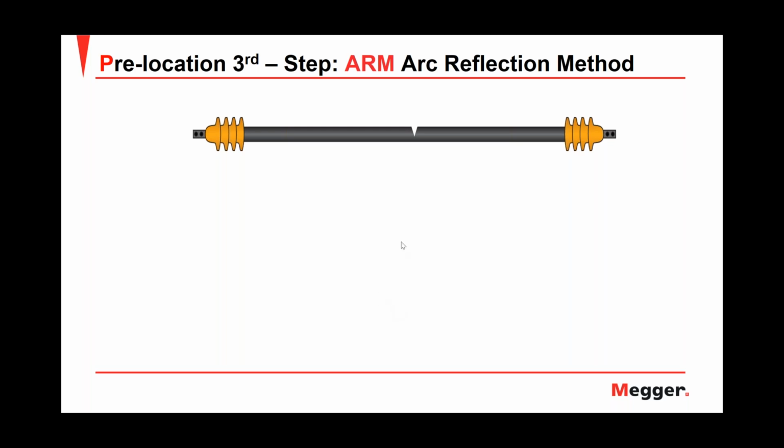Let's consider that we have a medium voltage cable. Let's say that it's a cable of 15 kV, and we have a pinhole fault over here. And this pinhole fault needs at least 4 kV to flash over. That means that the breakdown voltage of my pinhole fault in this cable, where it flashes over, is 4 kV. That is the breakdown voltage, 4 kV.